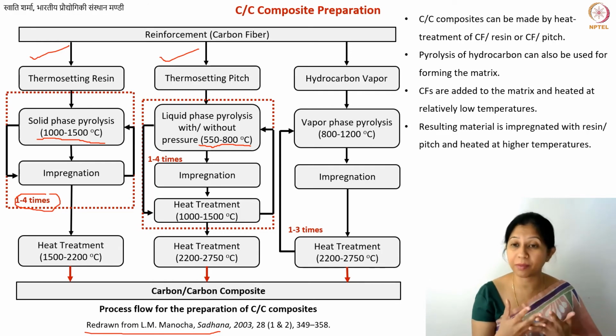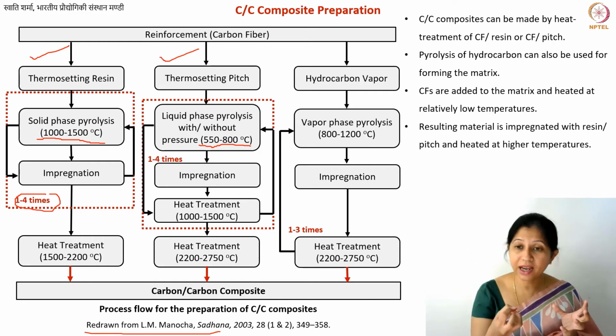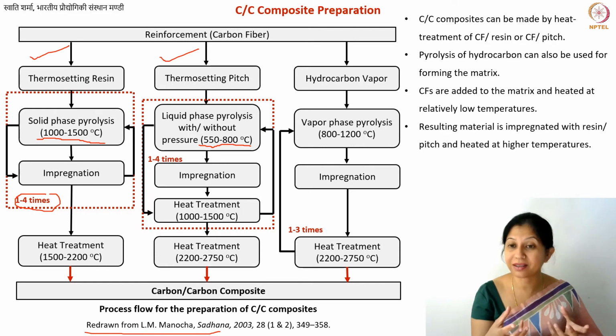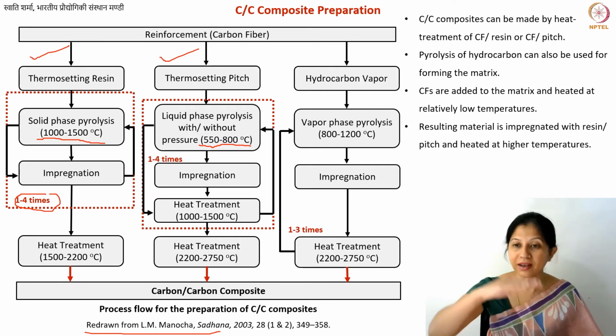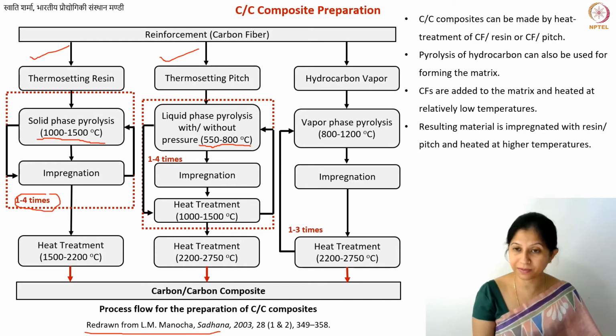So if you have carbon fibers, first let's start just with carbon fibers. If you have your fibers, then you heat them, and your hydrocarbons can actually crack on the surface of the fibers themselves and they can deposit. Then you will perform, as I said, some annealing, or depending on the structure, you can perform hot pressing, and then layer by layer you will make your pyrolytic carbon on top of this. This kind of carbon, because you don't have non-carbon atoms, you are able to control the porosity at every stage. However, you can imagine that this is a relatively much slower process.